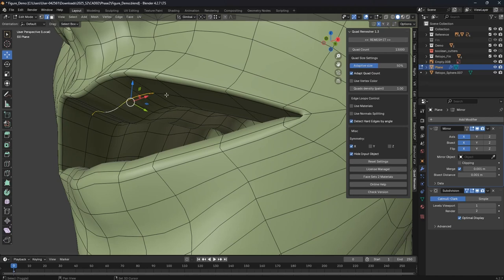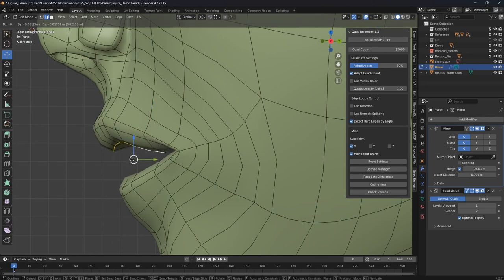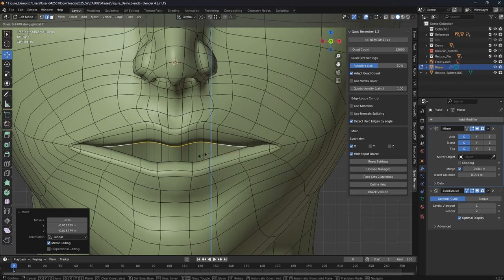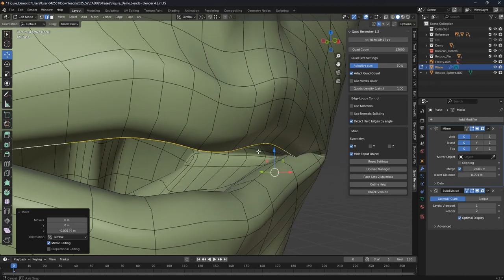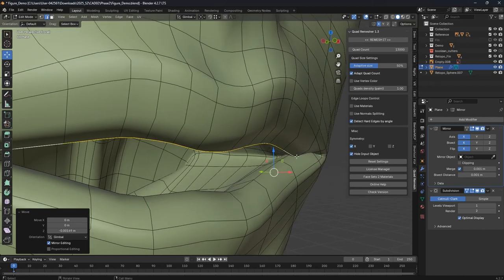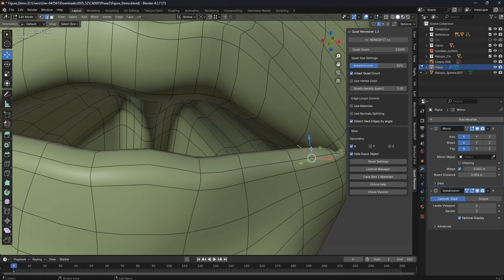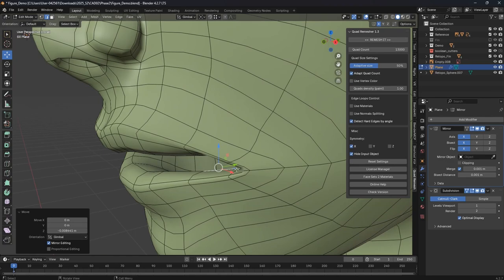Let's go to the side view and refine that. And probably you can make this one a little bit flattened. So let's press S and Z, flatten a little bit. Move this one going down. And if there is any part of the model that intersects, please fix that manually because this should not happen. So let's just use the edge selection mode and move them up. For this last part, nothing special, just work manually.